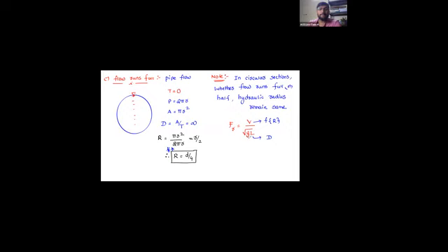Yesterday I told you, for analysis, we use average parameters. Are we using a rigid boundary canal or a mobile boundary canal? A rigid boundary canal. What is the degree of freedom? 1 or 4? 1. And what is that degree of freedom? Depth of flow. Are you going to take the maximum, minimum or average depth of flow? Average depth of flow. And what is average depth of flow? Hydraulic depth. So in order to classify the flow, you must know the shape of the section.